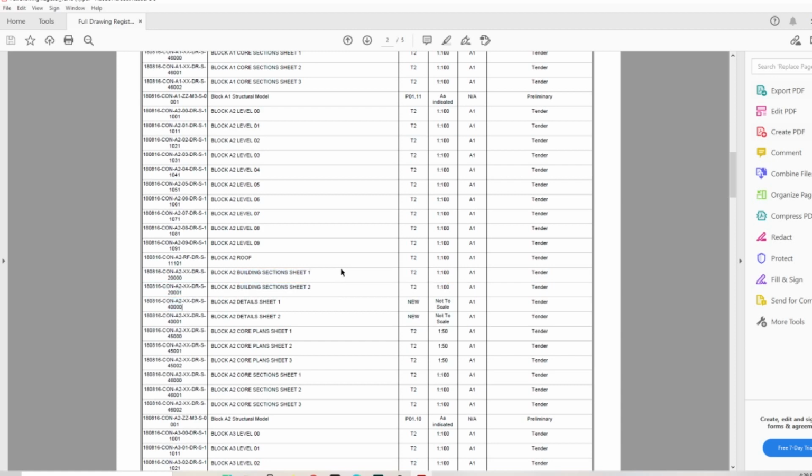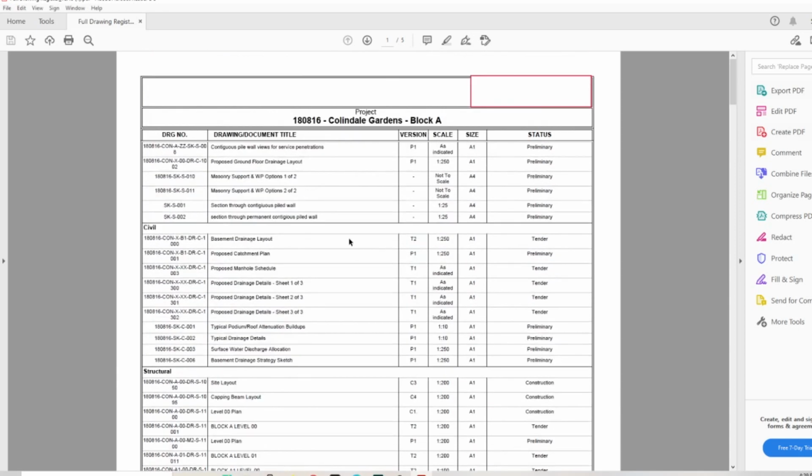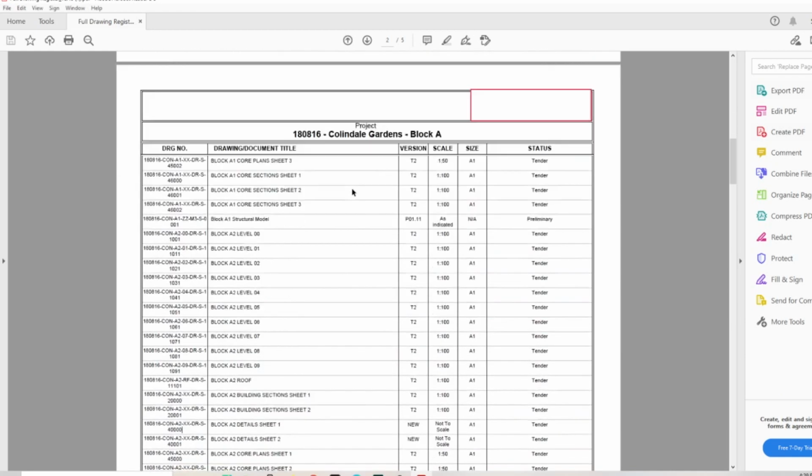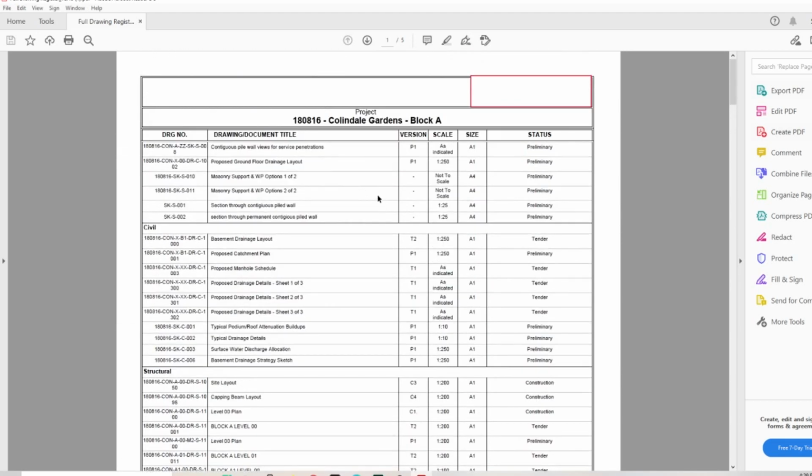And if you don't find it in the drawing platform, such as Asite or whichever platform you're using, there is something missing, so you need to ask for it, or you need to look for it deeper. So that will be the first thing. You want a drawing register in which you should find each drawing covering the structural part of your construction, drainage, and everything really. So the drawing register will be your first drawing needed as we start constructing elements.